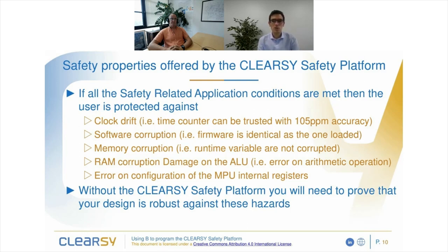You are guaranteed that the software that is executed is identical to the one you have loaded before. You are protected against memory corruption. You are protected against RAM corruption or damage on the arithmetic and logical unit, so when you perform 2 + 2, you always get 4, or the platform is in shutdown mode. And you are also protected against errors on the configuration of the peripherals and internal registers of the microcontroller.